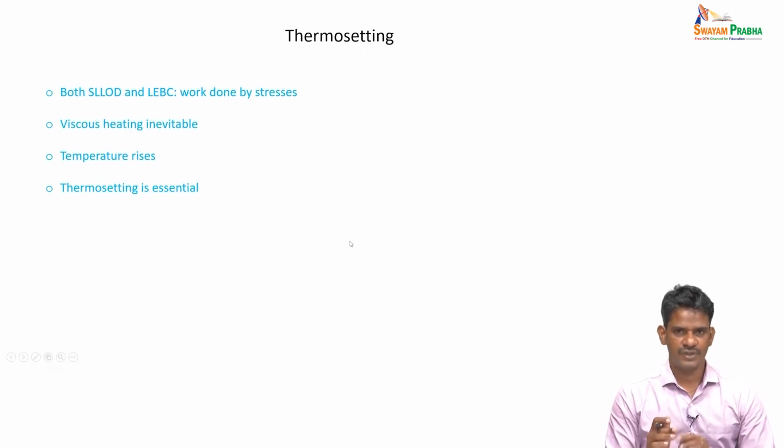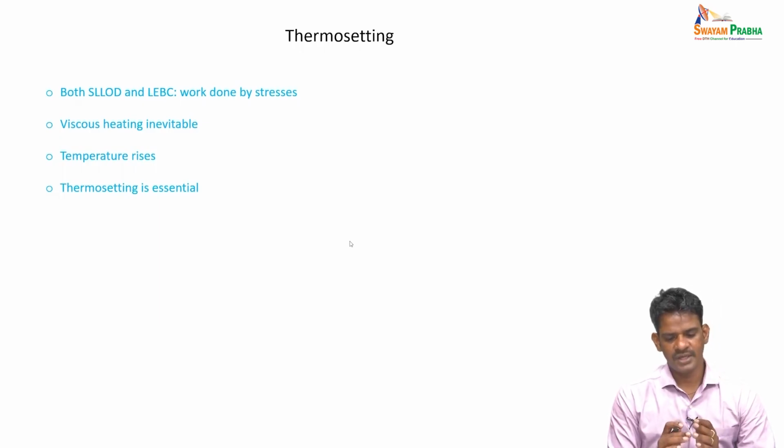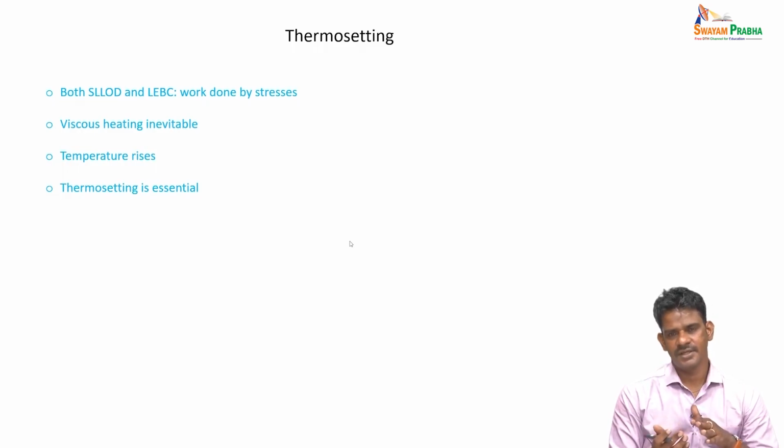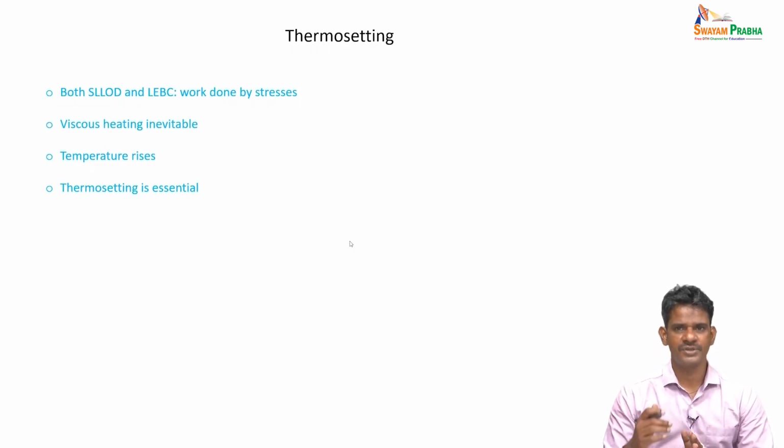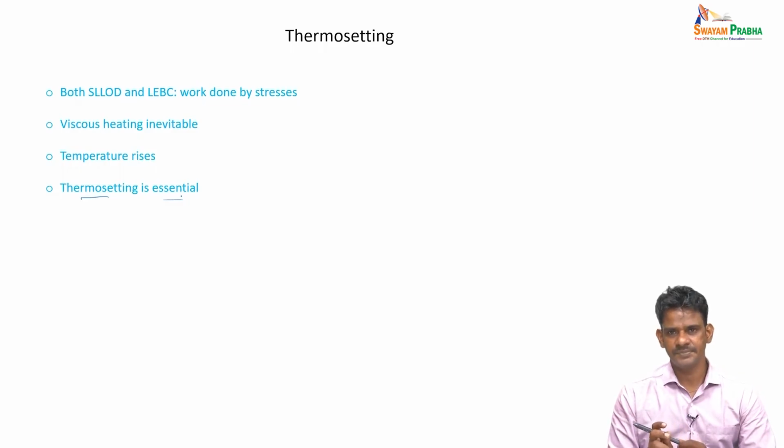So we talked about how to impose the shear on the particles and how to take care of the boundary, either using a box flip method or the Lees-Edwards boundary condition. Now, if you look at the simulation as it goes, you will see that the temperature in the system keeps increasing. This is because the shear induces viscous heating, and the temperature rise is inevitable, especially if you simulate for a very long time. So we also need to do something about setting the temperature to a constant value.